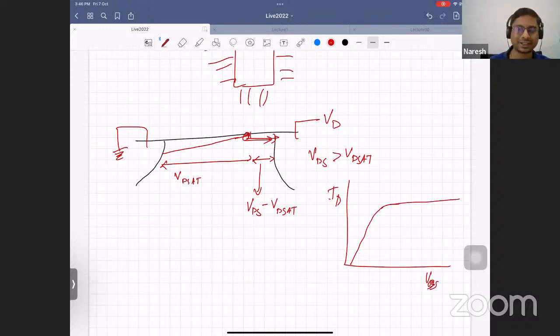In the classical long channel MOSFET, it happens. It doesn't increase because you're not having any additional carrier density. Finally, the density of this is what is going to determine how much current flows. Now the channel got pinched off. There's no further, additional electrons that are coming in.